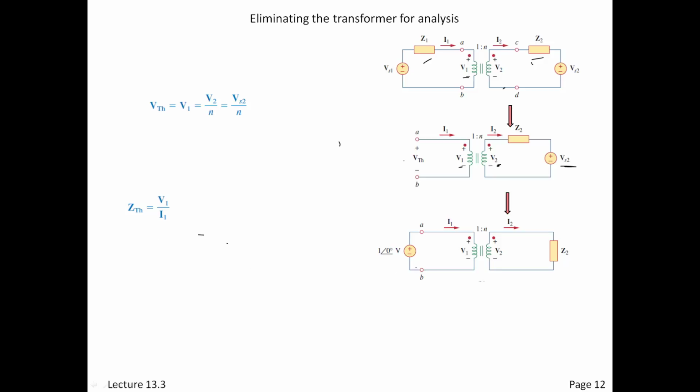We're right here. Thevenin, right? That's where we're looking. It's V1 over I1, where V1 remains the source over there. And so now we're just plugging and chugging in the usual way, expressing it in terms of I2, right? So you can see what we're headed for here.